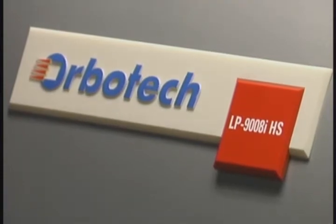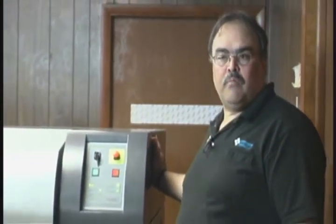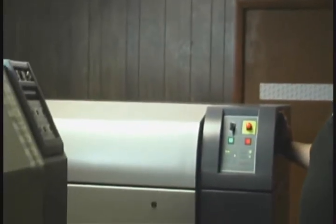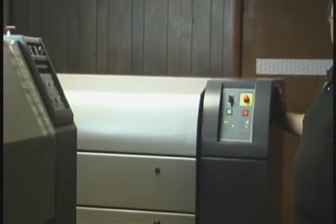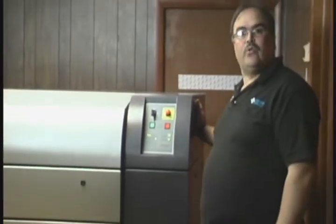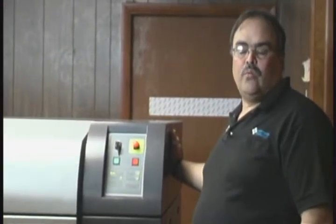We also use an LP 9008 laser plotter. This is the newer version of plotters from Orbotech. This plotter is dedicated only for our plotting services. We have the capabilities to plot film to a 1/4 of a mil resolution, a 1/8 of a mil resolution, or 1/16 of a mil resolution, according to what our customer needs are.